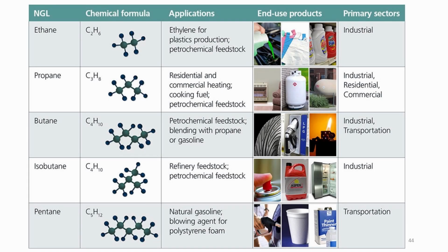During the Second World War, catalytic dehydrogenation of butanes over a chromium-alumina catalyst was practiced for the production of butenes that were then dimerized to octenes and hydrogenated to octanes to yield high-octane aviation fuel. Dehydrogenation employs chromium-alumina catalyst and, more recently, platinum or modified platinum catalyst.